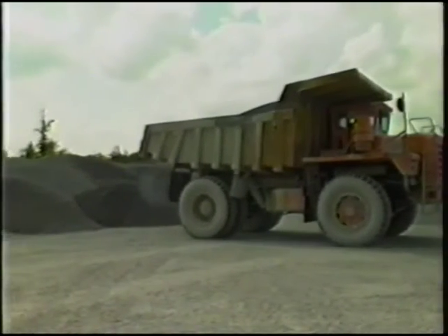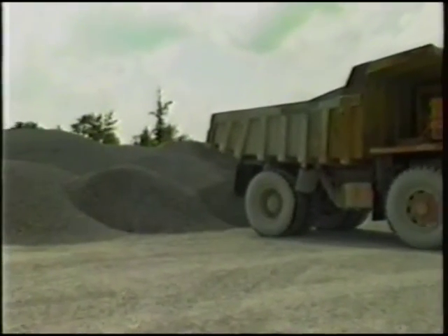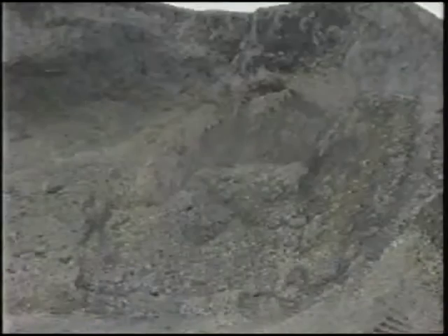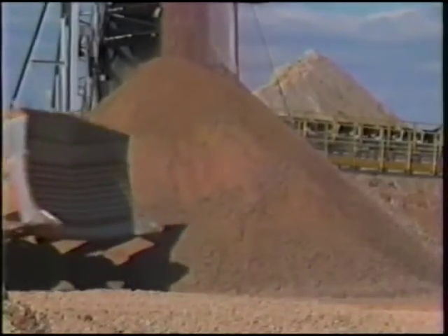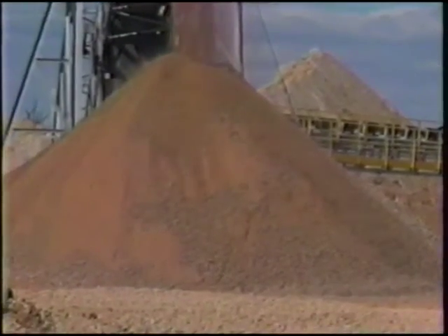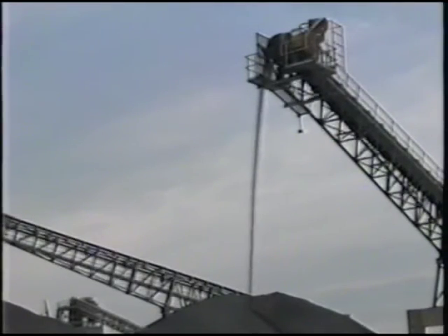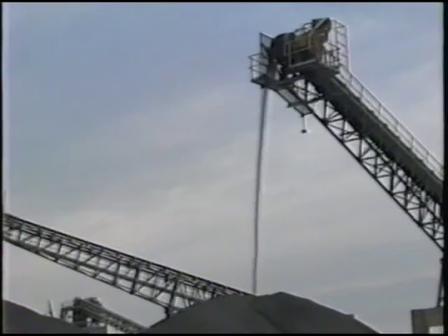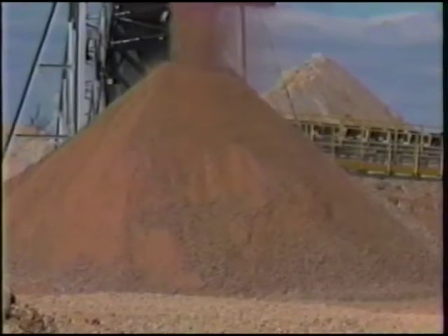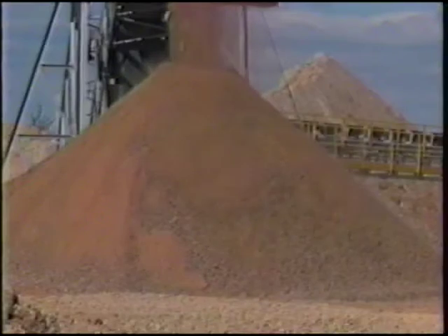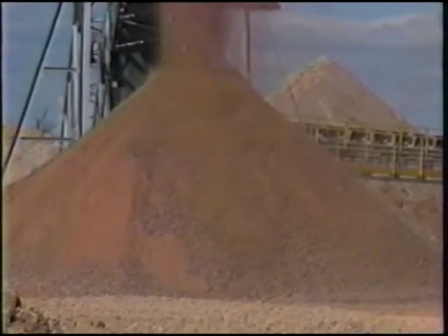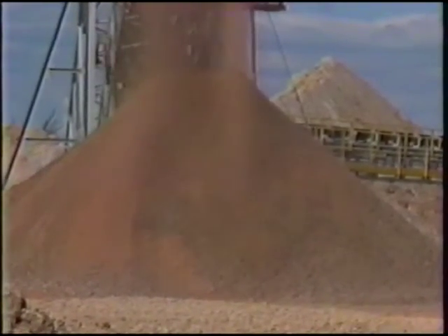Material segregation is one of the primary things to avoid when constructing a stockpile. Segregation occurs when the larger particles separate from the smaller ones. The result is coarse and fine areas within the stockpile. Because the material is no longer properly blended, it is not a desirable construction product. The most common cause of segregation is the larger particles separating in a fall or by rolling down the side of a pile. To prevent this from happening, make sure the aggregate does not fall or roll any more than it absolutely must.